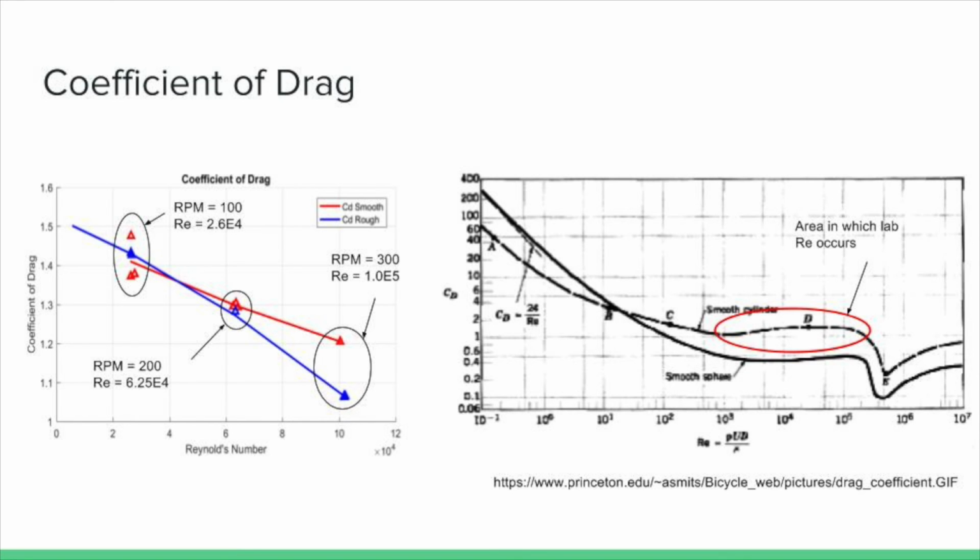It should also be noticed that in the 100 RPM runs for a clean cylinder, one of the calculated coefficients was much higher than the other two. This can be due to a possible error. It suggests that something changed between the runs, such as the outside door opening while we were recording data. Also, due to the low RPM of the fan, the amount of pressure felt by the cylinder is so low that the data collection is difficult.